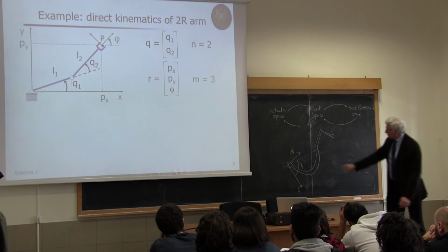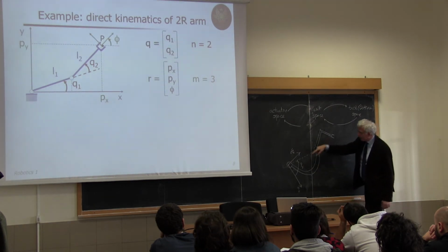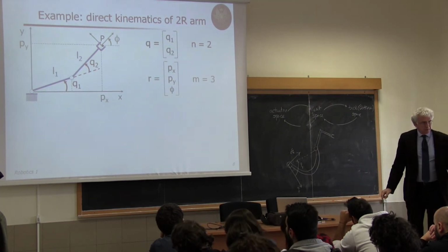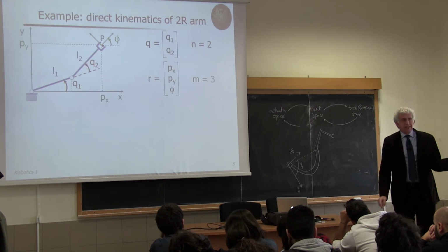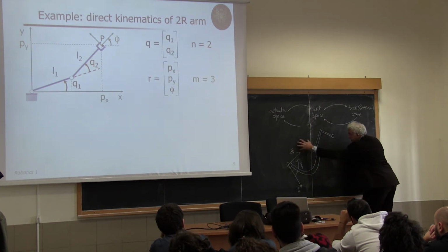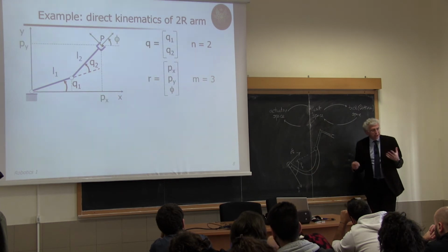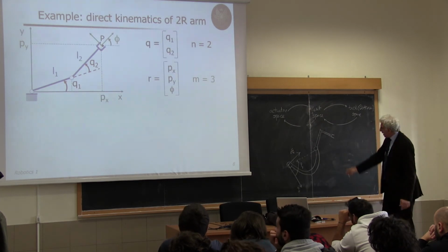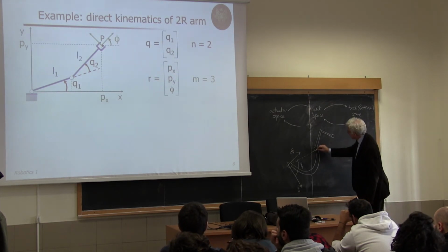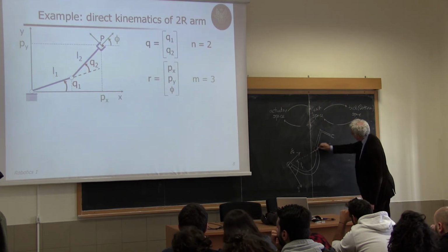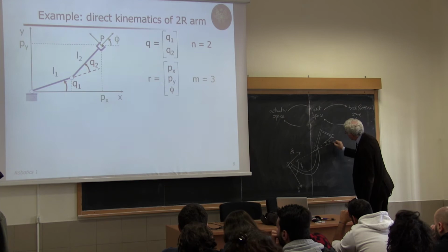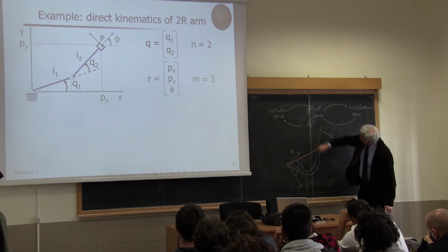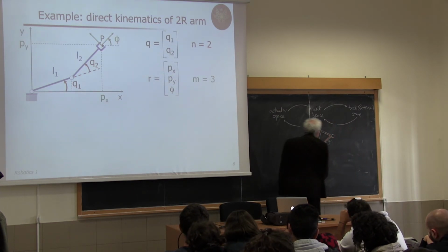Okay? So if this goes like a moon or like an S or is straight, it makes no difference at all from a kinematic point of view. It moves exactly in the same way. Sure, if I have an obstacle in the workspace, the geometric size and form of the link matters, but this is not our problem now. And again, here I can take the prolongation of this and then take this as Q2. So you see that for what it matters, this is like having this link and this link.